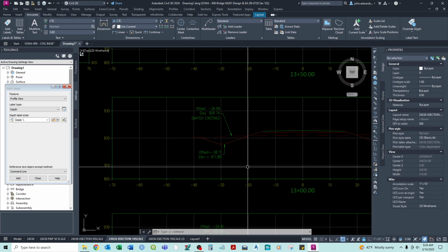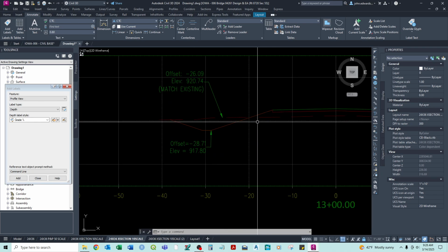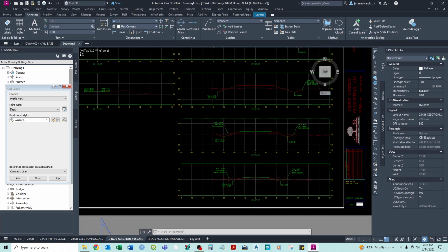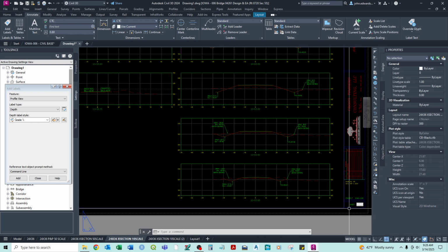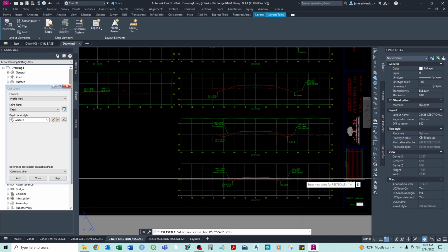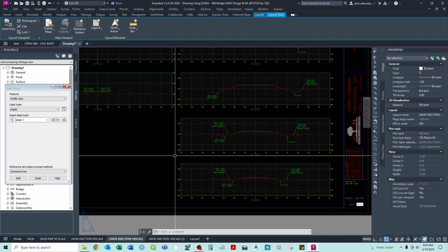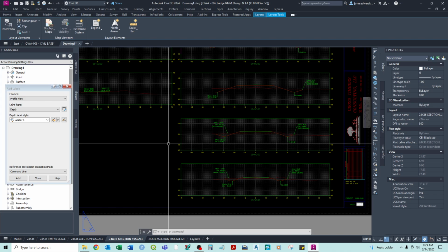But even here, sometimes the little dots that we're looking for may not always show up. And so there's a couple things you can change. There's the LT scale. We can change that between 0 and 1 normally. Oh, no, so that one's set to 1. I think it's the PSLT scale that we want to potentially manipulate. There we go. And see, now that changes.